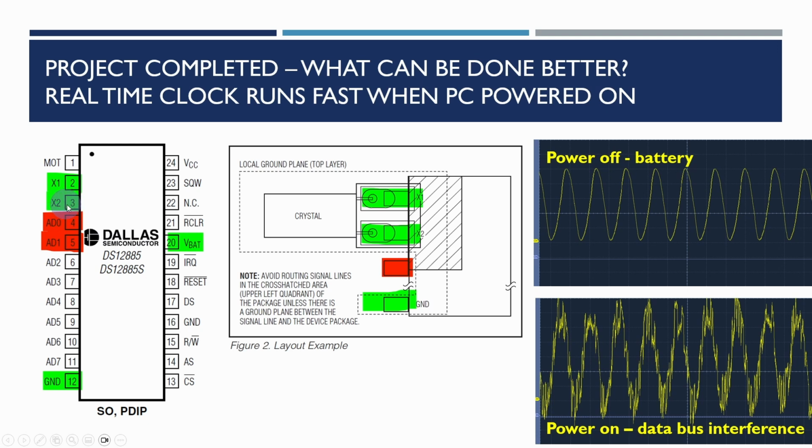What I was thinking of doing is perhaps bending these 2 pins out, soldering the crystal to the pins directly, and perhaps including some shielding from the other data lines there.